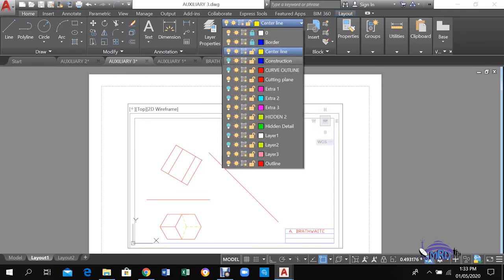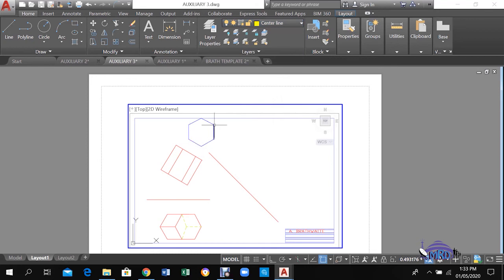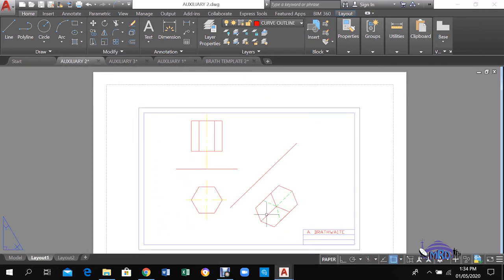So what I would have done in order to get this construction up is that I constructed the hexagon on the outside and then projected the corners so that I could get the shape of the front view. Having gotten the shape of the front view, I then project the corners down in the same manner as I produced the auxiliary before, because remember, this auxiliary would have had a similar look for the view.